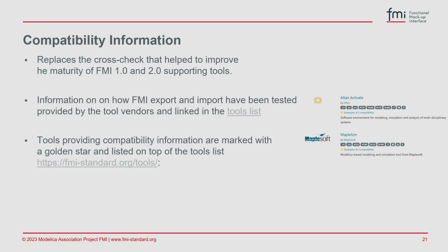On the FMI webpage you will also find a validation tab. We offer different checking tools, and I think Thorsten will show some of them in the second part. This is for validating FMUs that you get from somewhere. Typically you mainly detect faults in the XML. Lots of faults have been made in the past, but there are very good checkers where you can now say, okay, this FMU is corrupt. It also depends on what you mean by compatible. Do you mean, can you get a result from the other connection, or can you trust the result?